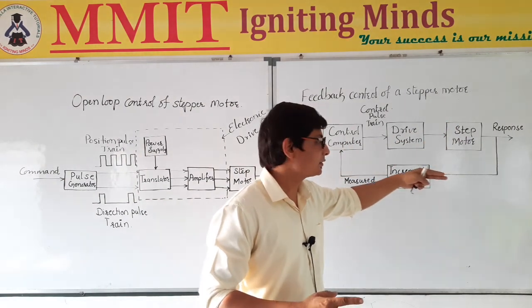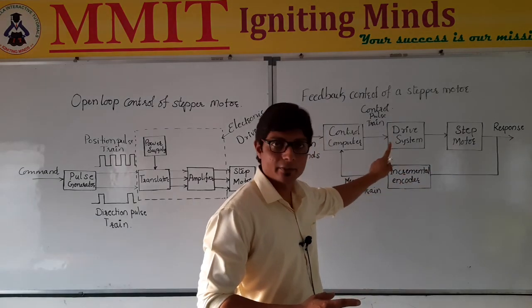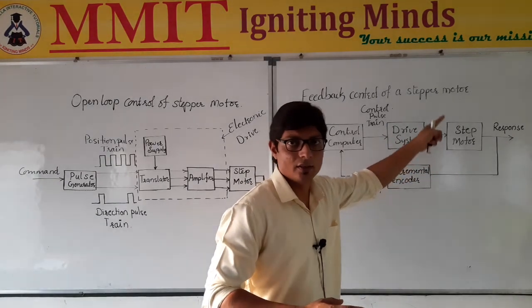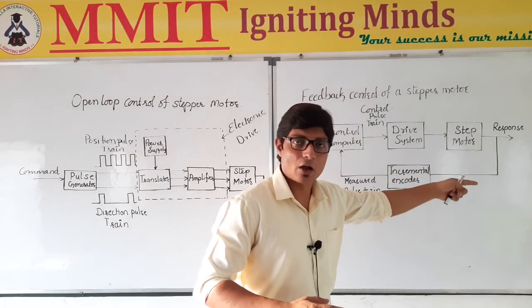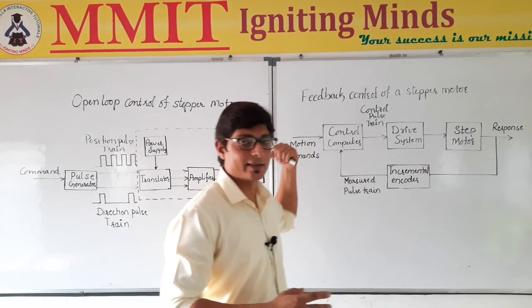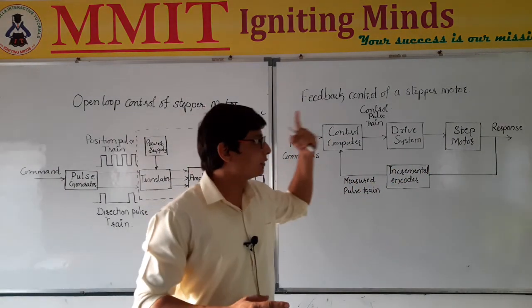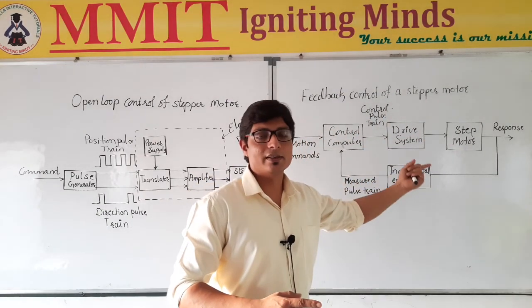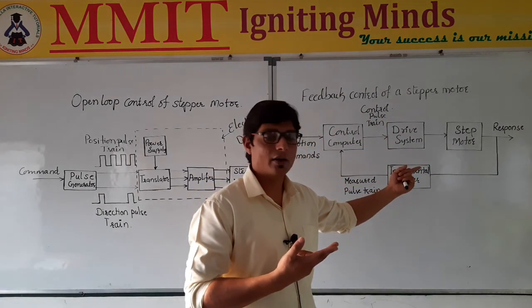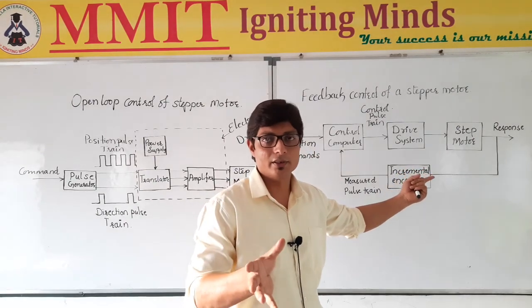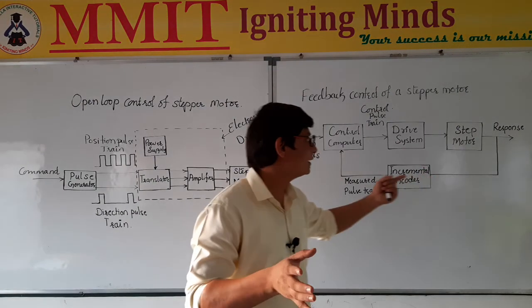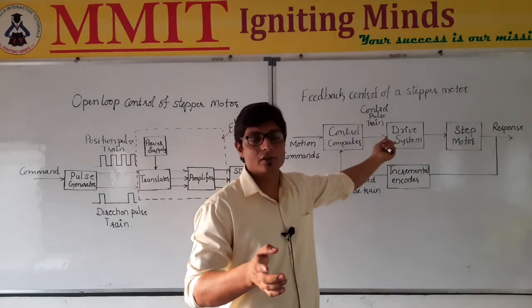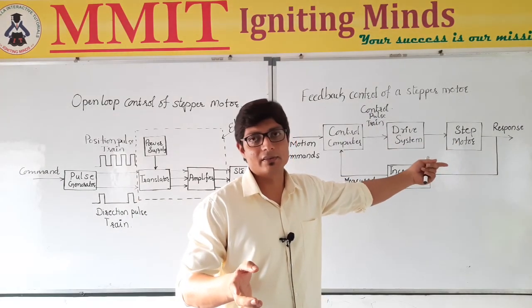When the rotor rotates by a certain angle, the count is incremented by 1. Likewise we come to know whether as many steps have been rotated by the motor as decided by the command signal. Only if the steps obtained by the step motor correspond to the pulses previously supplied is the next pulse train given to the driving circuit.